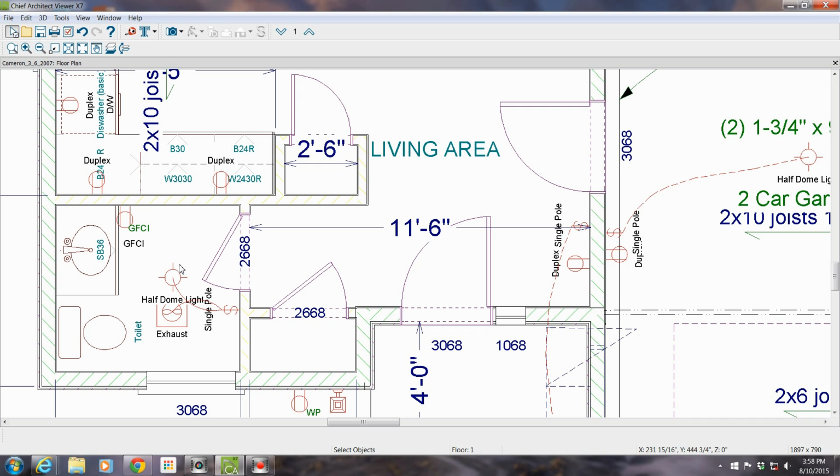A light fixture in a ceiling is always noted, the circle with the 4 lines coming out. And then when you have that, you'll see a line going back to the wall someplace. You have an S with the line through it. That's the universal sign for a switch. So the switch, and you can follow the line, operates that.